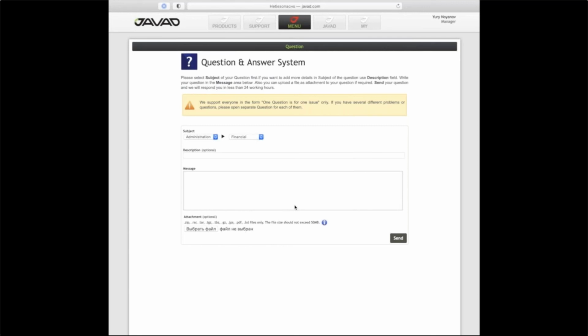After that, the receiver will get corrections of the coordinate system and apply them inside the receiver firmware, and you will get not just, for example, latitude and longitude, but east and north coordinates already applied with the corrections.